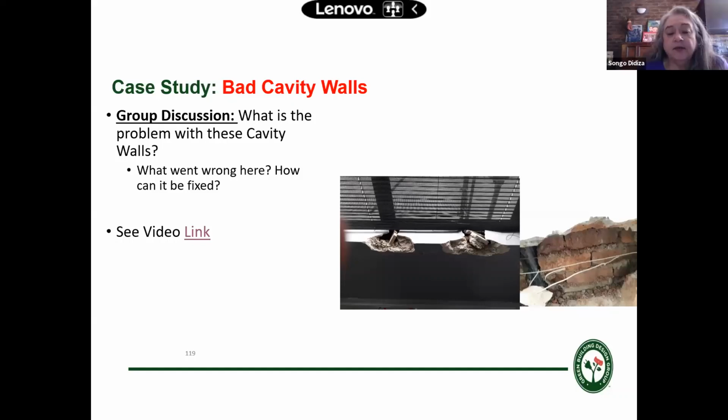The difference is that lightweight construction depends totally on the R value to give energy performance, whereas masonry walling or heavyweight construction has a combination of thermal capacity plus some insulation. And when we look at cavity walls, we don't want cavity walls filled with anything, because then they are no longer cavity walls, they are solid brick walls, solid walls.